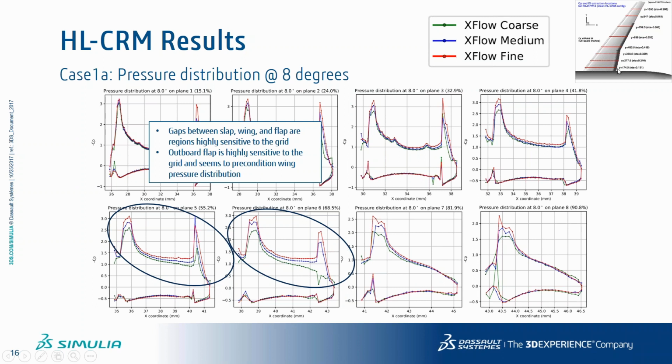And as you may know, the gap between the wing and the flap is reducing as you go to the outer, let's say at higher span position. Okay, so basically the gap is very tiny in these areas here, whereas it's larger in these areas here. It's important to resolve this gap in between the blade elements very well to resolve the flow mechanism correctly.